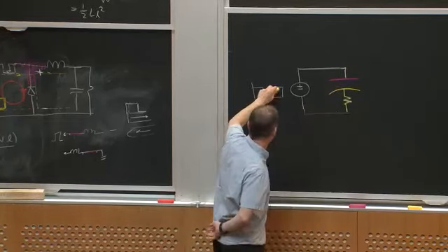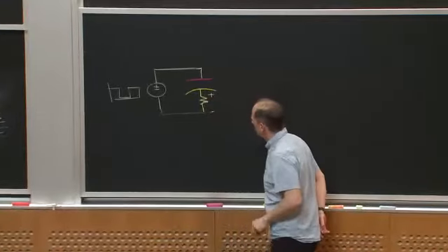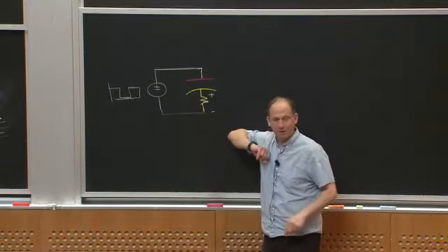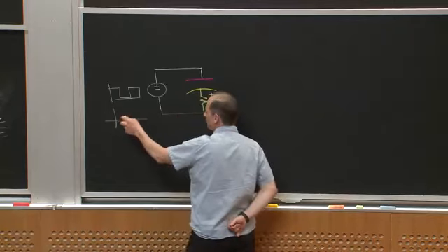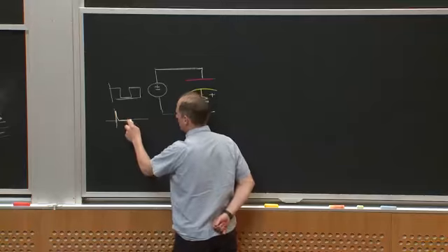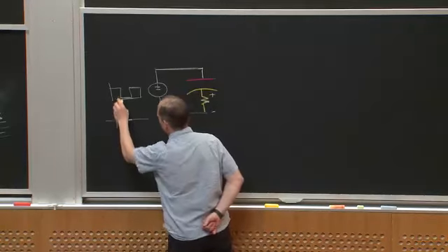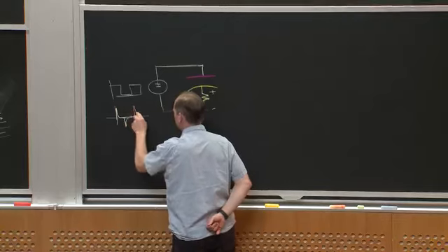So if this voltage is here, what is the induced voltage? Well, simple RC divider, what does that tell me? It tells me I ought to be seeing a voltage that spikes up and rings down, and then spikes down and rings up, and vice versa, right?